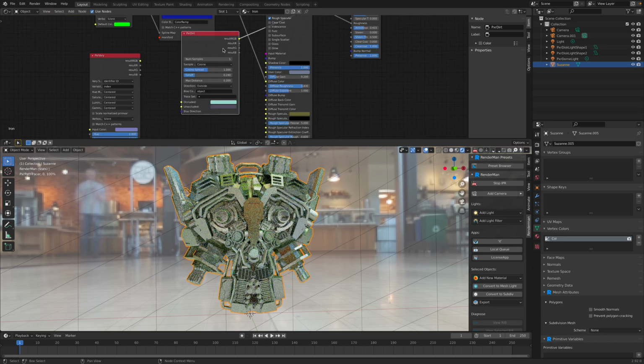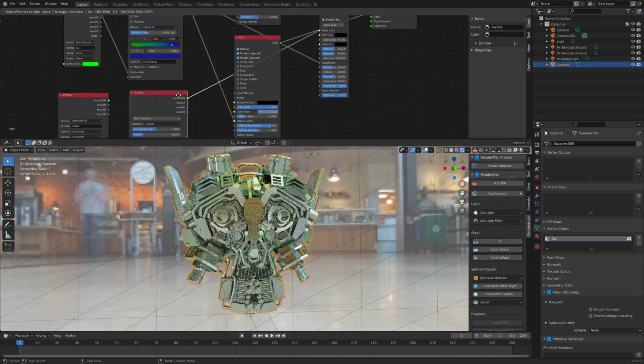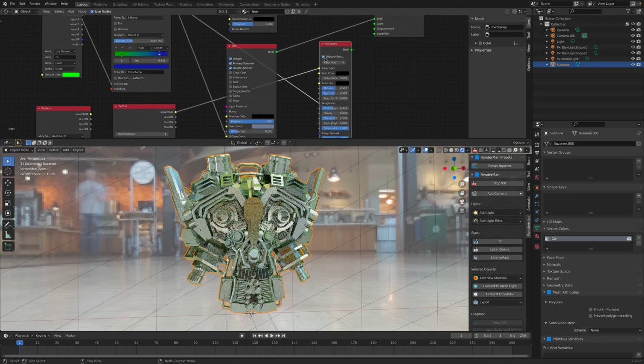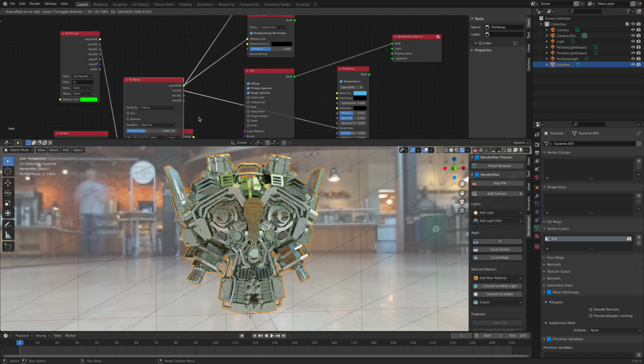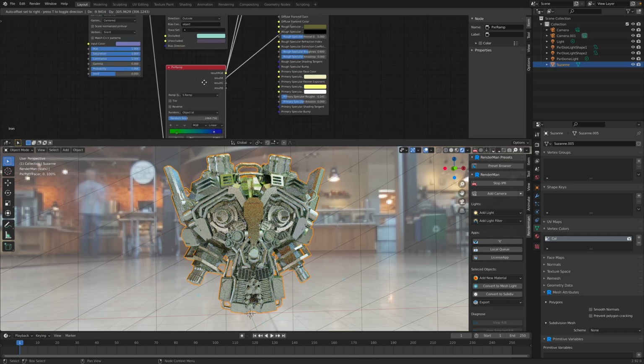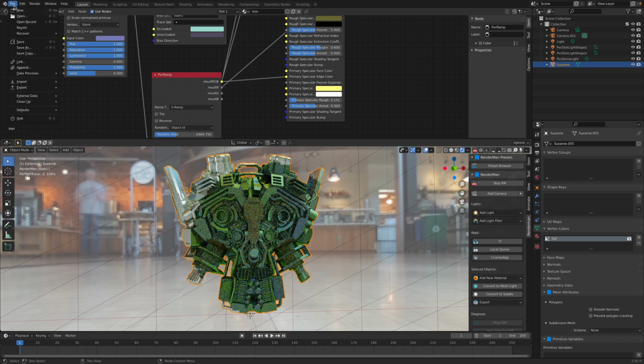There's also this dirt shader that I was testing out earlier. The dirt shader actually looks quite beautiful if I simply plug this into our diffuse, for example. I should mix the diffuse color and the PxrDirt. This is a little like ambient occlusion, just a little bit dirtier. It's nice to have this. The RGB result can be plugged into the specularity too. Now it's getting a different look altogether. I actually quite like this. So this is getting variations.